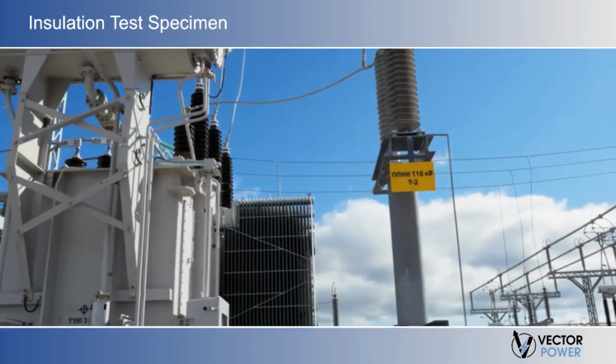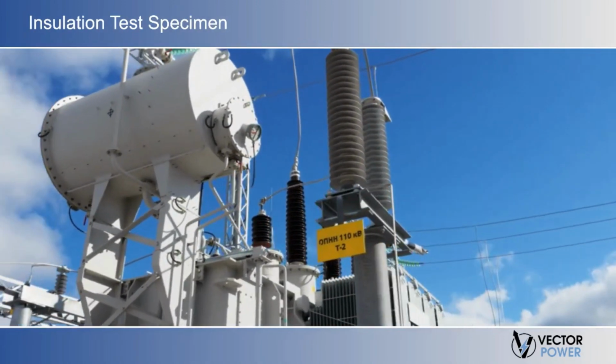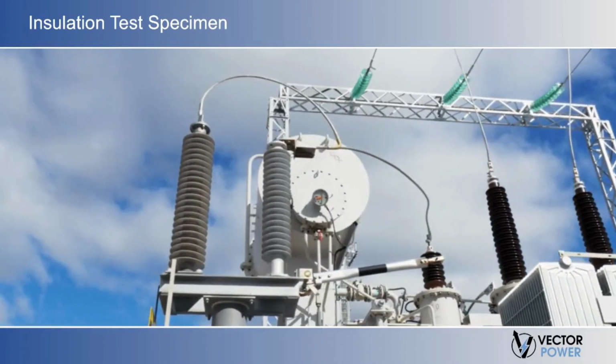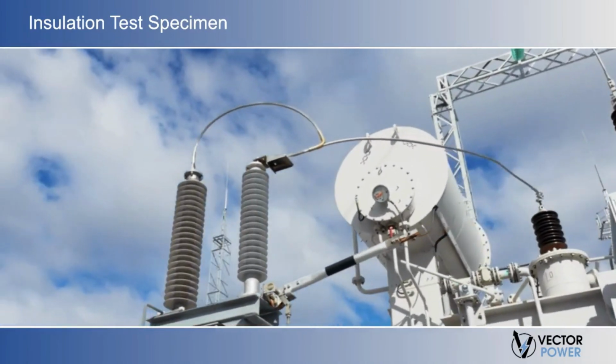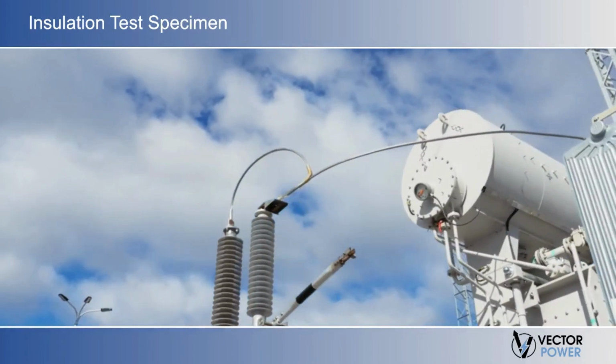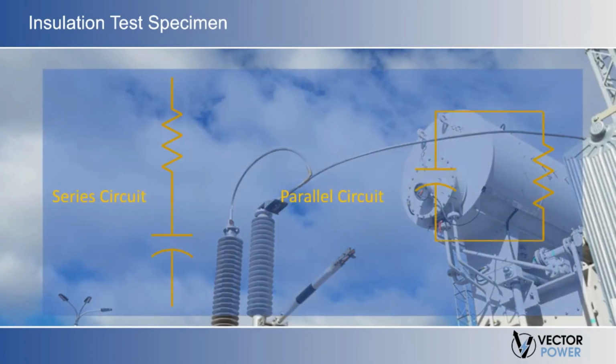Now, insulation systems associated with many types of high voltage power apparatus and devices often consist of a mix of non-homogeneous component parts. As such, a complete and highly accurate schematic representation of an apparatus insulation system may be quite complex and difficult to compose, perhaps consisting of several resistor and capacitor elements arranged in many various ways.